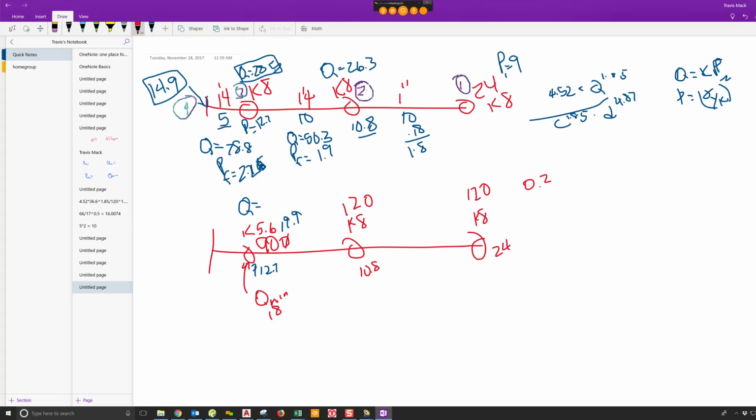Okay, now we've met the criteria is that we have to make sure that this head can meet or get its minimum discharge. It's only kicking out 19.9 gallons versus the 18 that it needs as a minimum. But here's where you see the big difference. See, this was 19.9 gallons here, 28.5 gallons here.